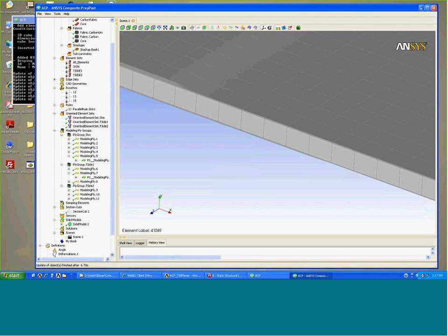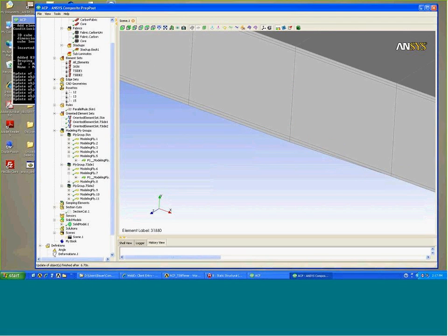These face sheets are rather thin, but we can see in this region where our rule cut that ply off, it now tapers that ply down in the region. Essentially, the rule cuts it off here and tapers that off. So this allows us, using rules, to define the shell section definition for analysis for different ply regions, as well as implement that in our solid model building.